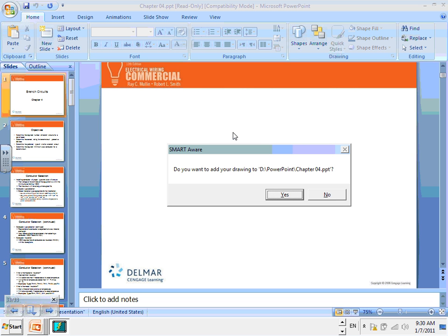If it makes sense to you, load modifier meaning because it's continuous, you have to multiply. I'm reading, by the way, at page 55. I switched into the upper right corner of page 55 because that's how it continues. Load modifier type is C. Load modifier is 1.25. Overcurrent device or overcurrent selection current: you take the 1.25, multiply it by the full load current. So you need 9 amp cable. Overcurrent device is a 20 amp because we don't want to use less than 20. It's a commercial building, remember.